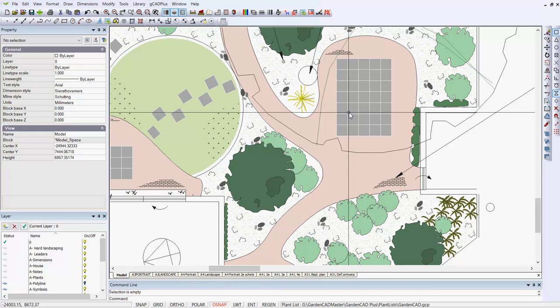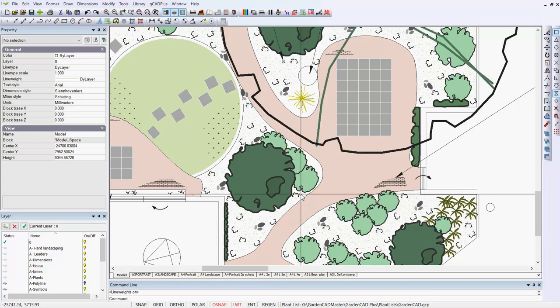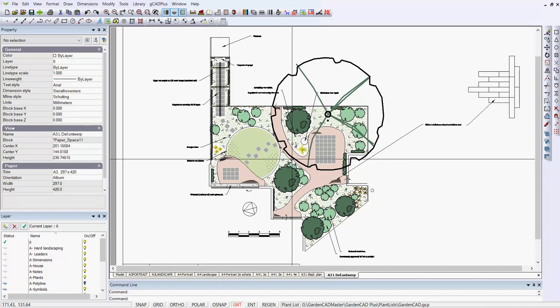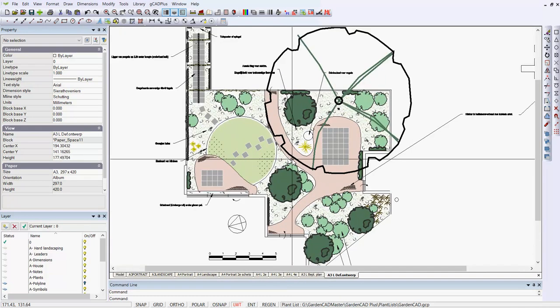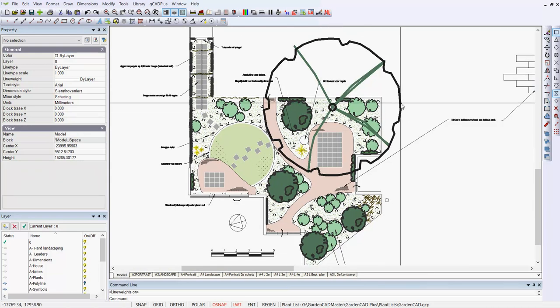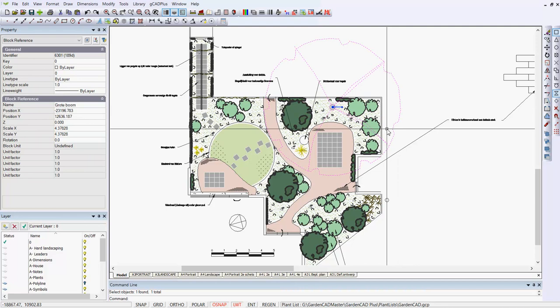If I turn line weight on, you'll notice quite a dramatic change. And if I zoom out here, can you see the thick line weights now show? If I go back to the A3 version, you may or may not like that effect. To mine, that's a little heavy, and if I go back into the model, I'd be inclined to pick this symbol here.